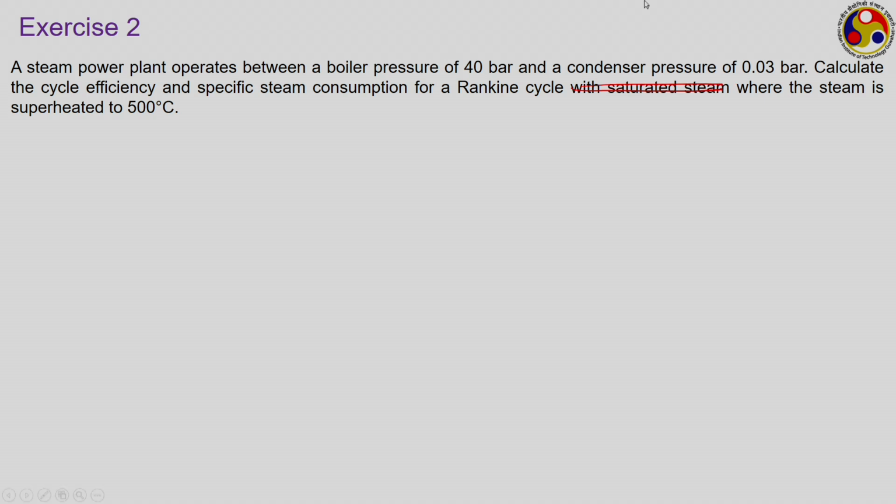Here the steam has been superheated to 500 degree Celsius. So, your H1 corresponds to a situation where your pressure is 40 bar and temperature is 500 degree Celsius. It is superheated; this temperature is well above the critical temperature.